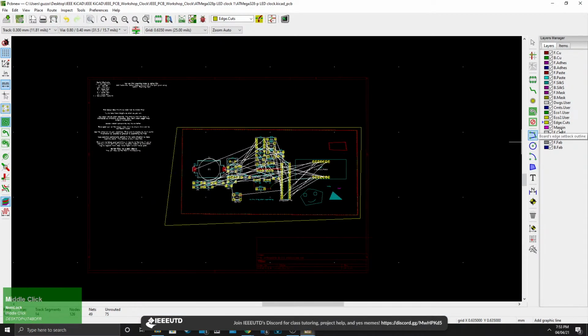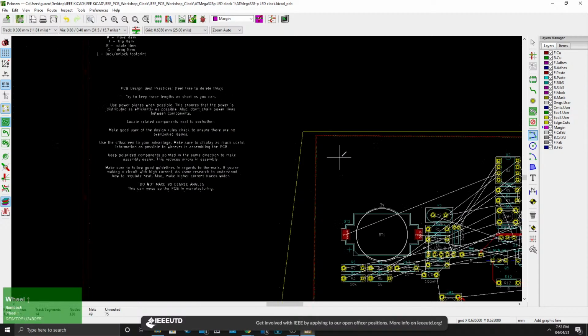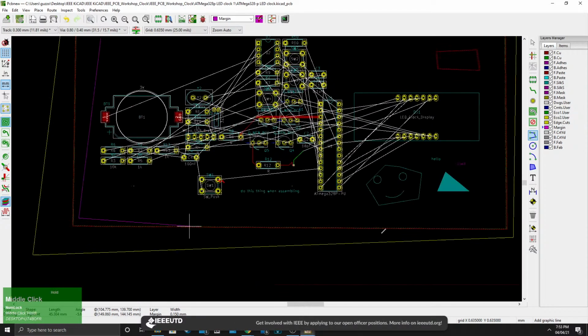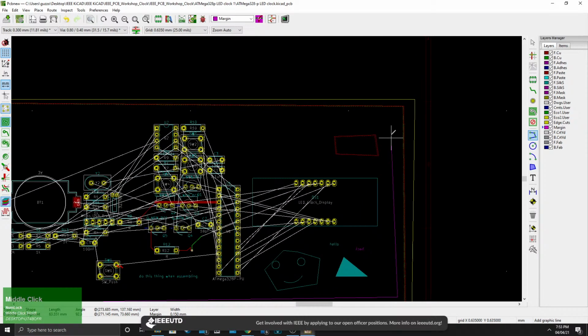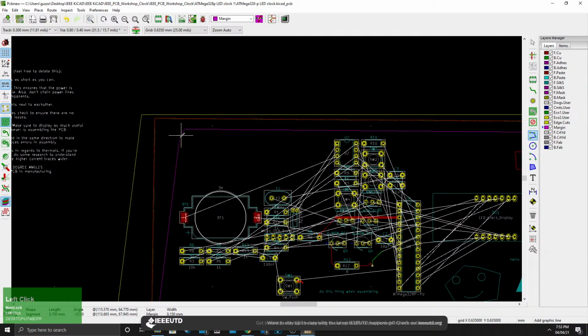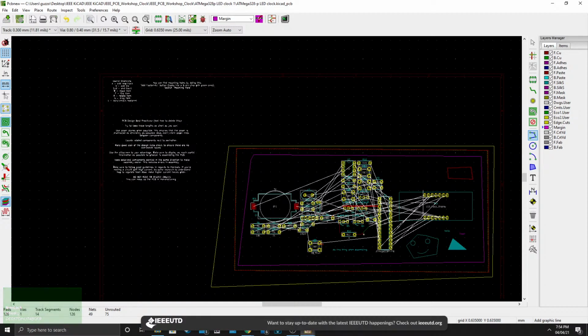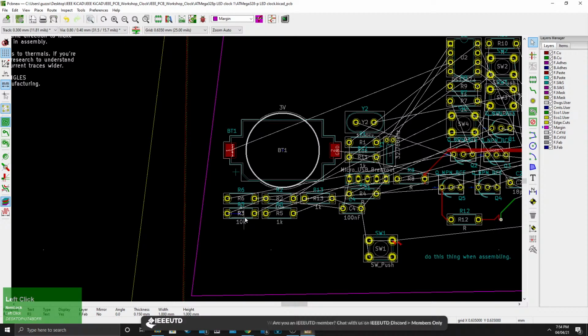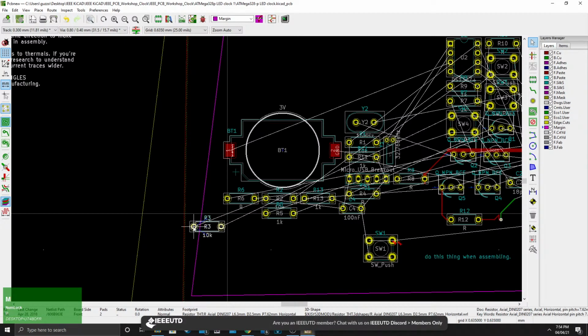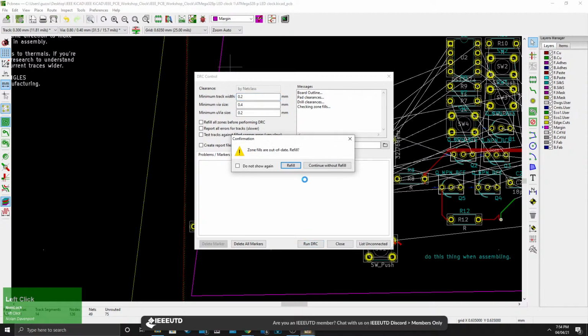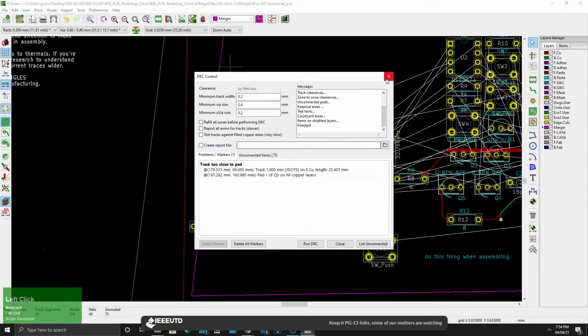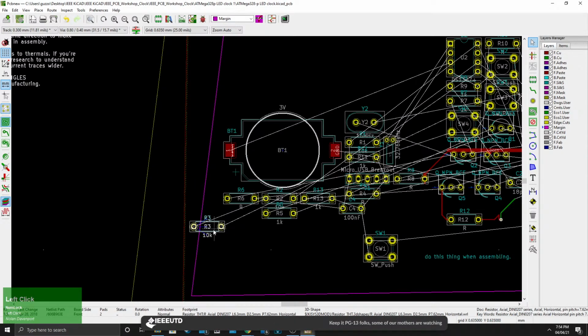All right. Then you got a margin that's deprecated. That essentially says components can't go past this point. But it's not really enforced, so it's a visual thing for people if they want to tell themselves, hey, I don't want to put components past that point. There's a chance it might put an error in the design rules check. If I put that there and then do a design rules check, continue, it doesn't. Well, I guess it's just a visual thing.